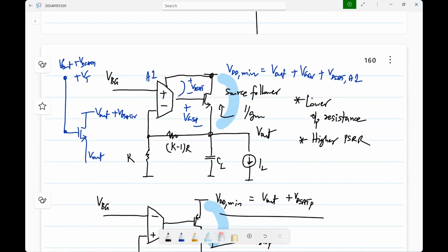So that's basically the difference between VDD and the highest output of the first stage. Okay. So you can see the dropout here is a lot larger than the dropout there. Okay. So if we consider VD sat to be 0.2 volts, the lower circuit can be made with a dropout of 0.2. That is minimum difference of 0.2 volts between the supply and the output. What will it be for the upper one with the normal parameters that we have been considering? Let's say VD sat is 0.2 volts everywhere. What is the minimum dropout?